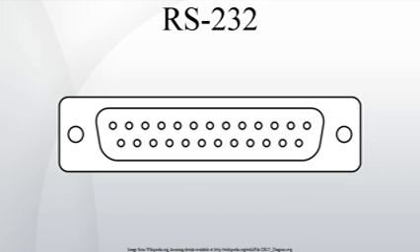Connecting a fully standard compliant DCE device and DTE device would use a cable that connects identical pin numbers in each connector, a so-called straight cable. Gender changers are available to solve gender mismatches between cables and connectors. Connecting devices with different types of connectors requires a cable that connects the corresponding pins according to the table above. Cables with 9 pins on one end and 25 on the other are common.